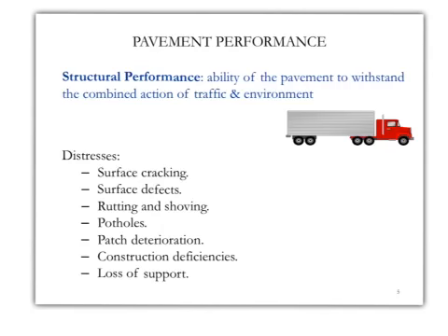How about now the structural performance? The structural performance is really the capability of the pavement to withstand the combined action of traffic as well as environment. We all know that the pavement has to interact with lots of traffic loads, but not only that. We also typically deal with different types of weather conditions. So I may have, for example, a shoulder on a highway that doesn't deal with much traffic but still fails, or we see some thermal cracking. So what's the reason here?